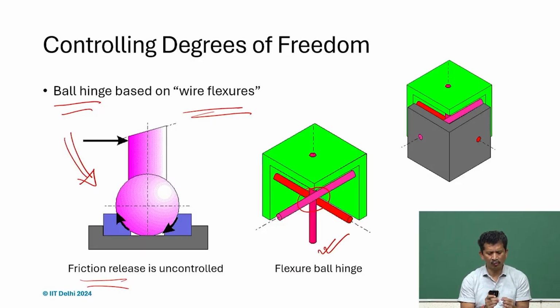So, we cannot get the exact pole, but slightly off, but for many applications it is good, and the offset we can always measure with respect to the rotation and compensate for that. So, this is using simple wires, maybe 1 millimeter, 0.5 millimeter steel wire with 20 millimeter or 30 millimeter length, which may be sufficient for many applications.